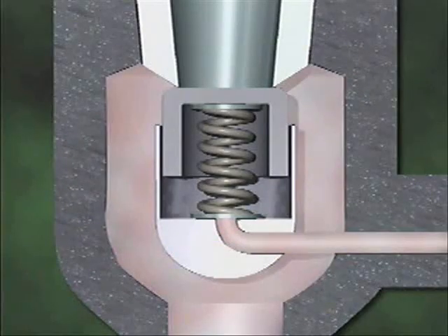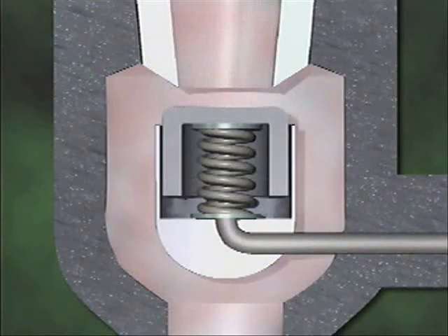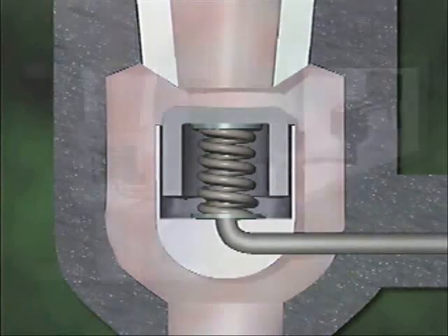The excess pressure that's relieved by the pilot valve comes from below the disc in the main valve. The amount of pressure that the pilot valve is capable of relieving is greater than the amount that could leak between the disc and the disc guide. When this pressure is relieved, the only pressure that remains on the disc is the pressure that's above it. With no counterbalancing pressure below the disc, the pressure above the disc easily overcomes the spring tension, so the valve opens to release system fluid through the outlet above the disc.